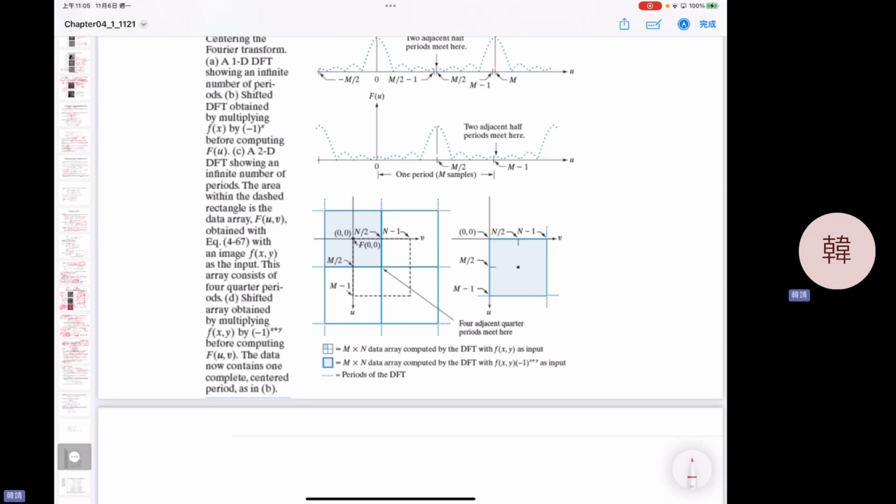So this is the idea. The sampling rate should be high enough, delta t should be very small, and in that sense the periodic signal in the frequency domain will not overlap, and you will not lose your signal.